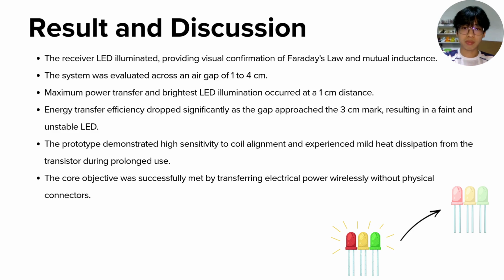We tested the system across a 1 to 4 cm air gap. Performance was optimal at 1 cm. However, as we approached the maximum 3 cm mark, the LED grew faint and unstable. This is expected as magnetic flux linkage drops rapidly over distance.